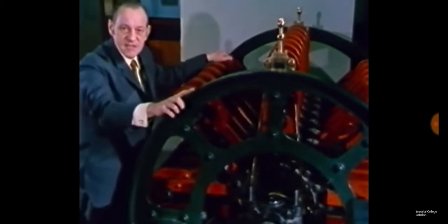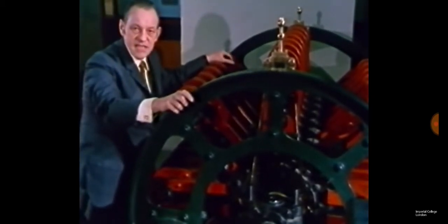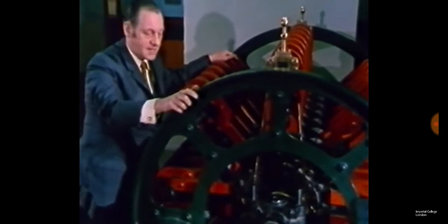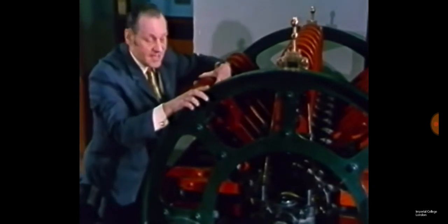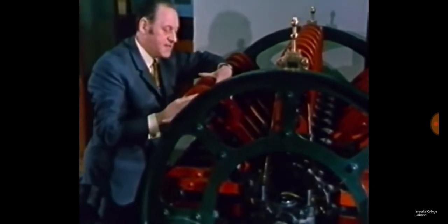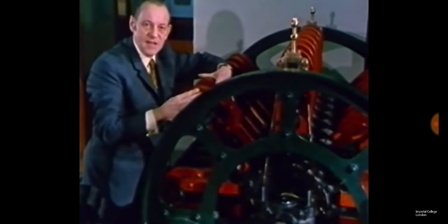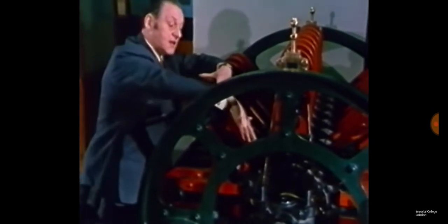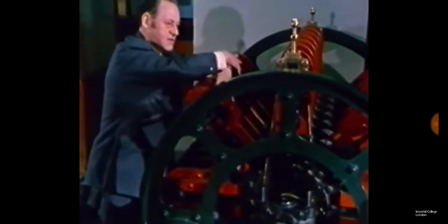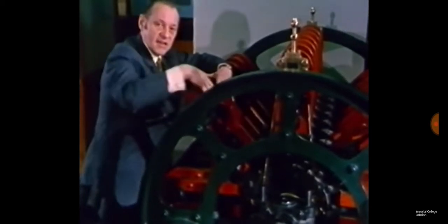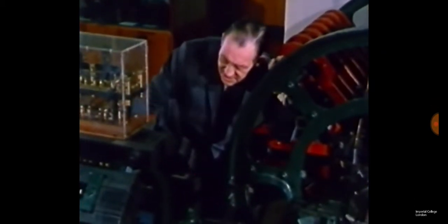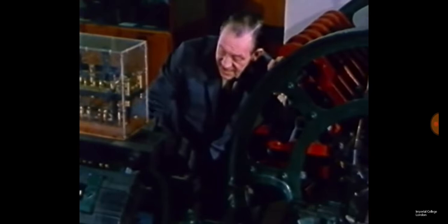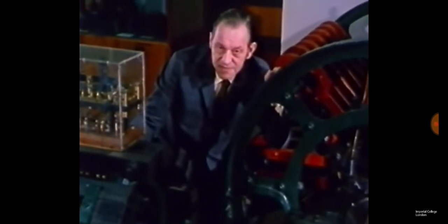When you look at the size of this mechanism and realize that the output of it was less than 2 kilowatts, then the shape just had to be wrong. One of the difficulties that designers of this period got themselves into was that they believed, quite wrongly, that you made better magnets when you made them long. So they finished up with all this wasted space through using these long magnets. And they made the same mistake with the previous machine, although in this case the magnets were arranged axially. But again, notice the long length of horseshoe magnet.